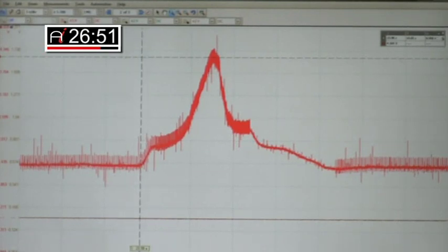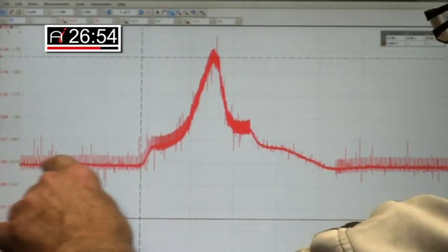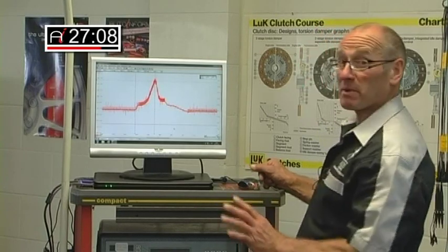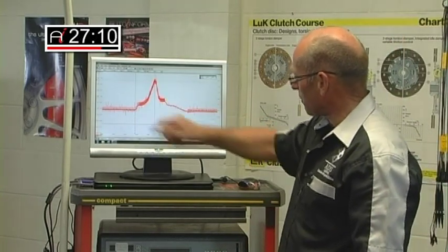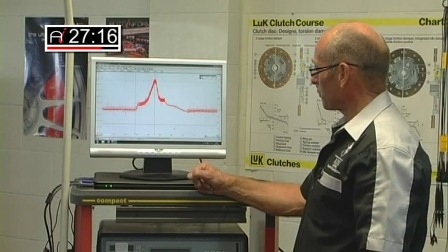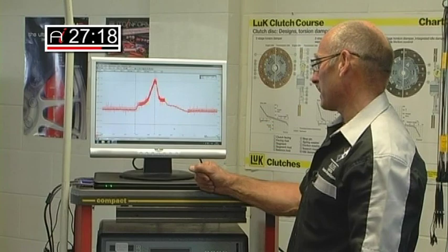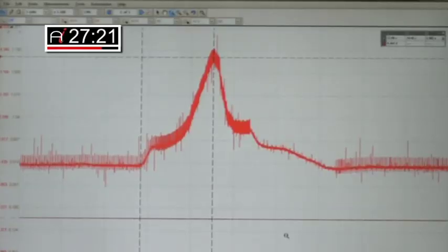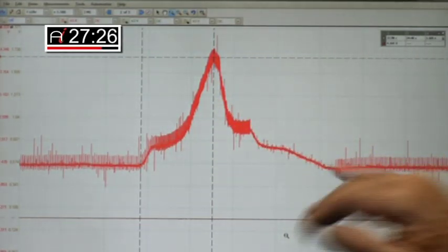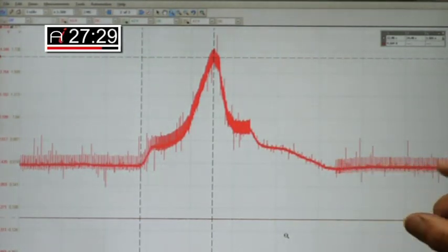we'll take a plot, because this is now at 300 bar at idle. And I'm also going to take a mean average of the maximum pressure, and that's taken 1.5 seconds. There again, I'm quite happy with the results. I'm happy because of the profile. 1 second would be nice. It's a little bit over that, but I have no problems at all with the shape and profile of that. Equally, when we lift off, want to watch it smoothly achieve the 1.3 volts.